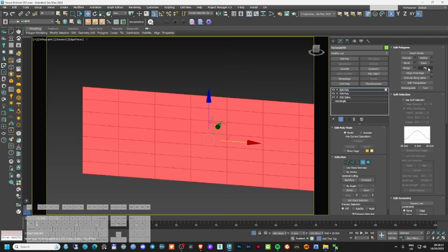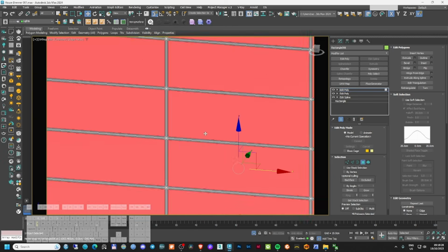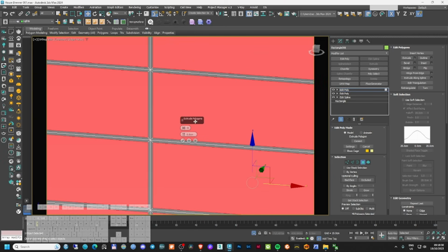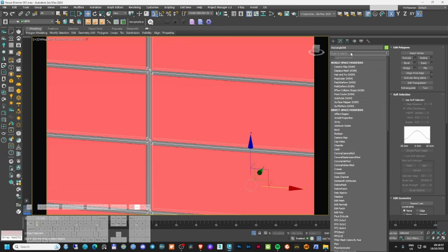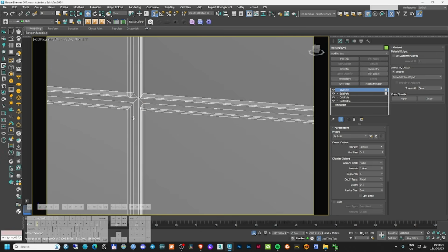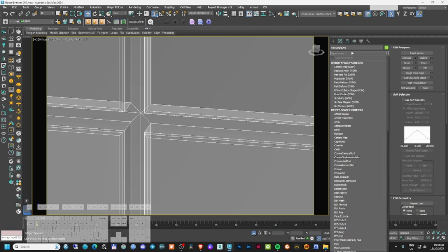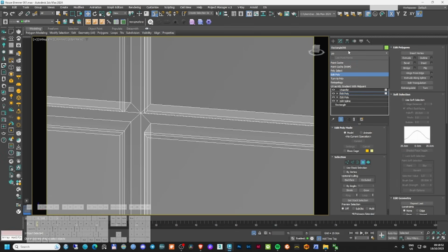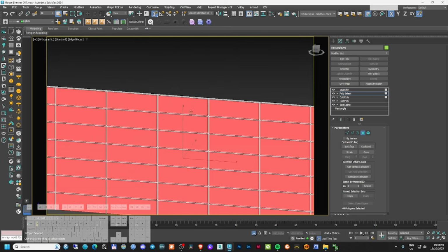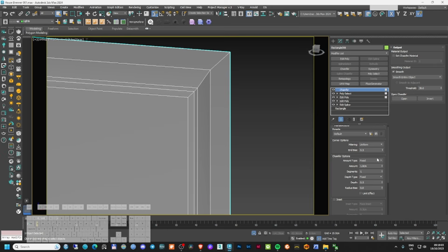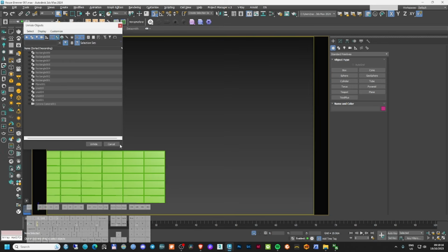So I will inset the whole thing a little bit by polygon, and after that I will extrude the whole thing a little bit, and then I will apply a chamfer to it. And because I had a selection, the chamfer is gonna go only on the selection, so I can add in here a poly select, and the moment that I click on the polygon, because I had a selection before underneath, it is going to select everything. Now if I apply the chamfer it is gonna go only on the selection. Okay, so we have the door from the garage also.